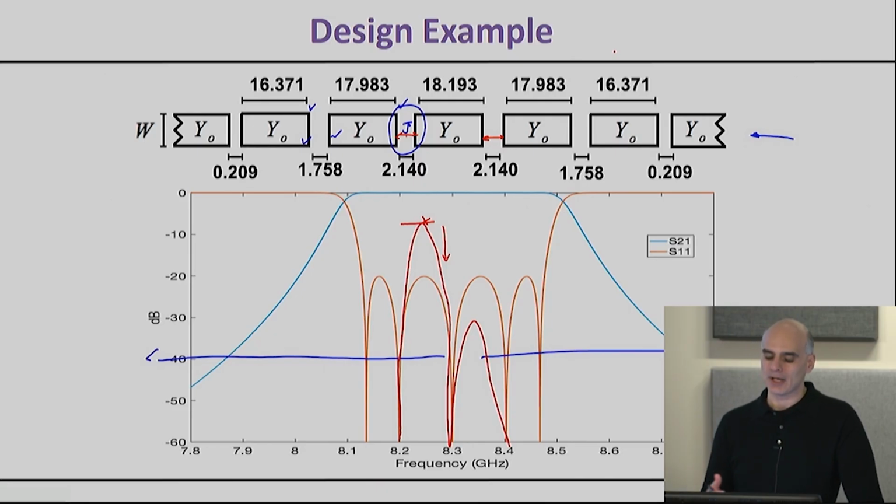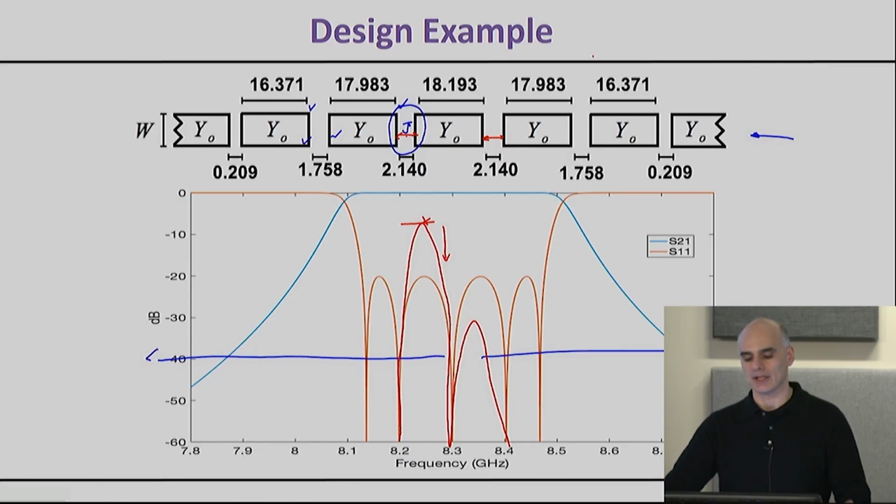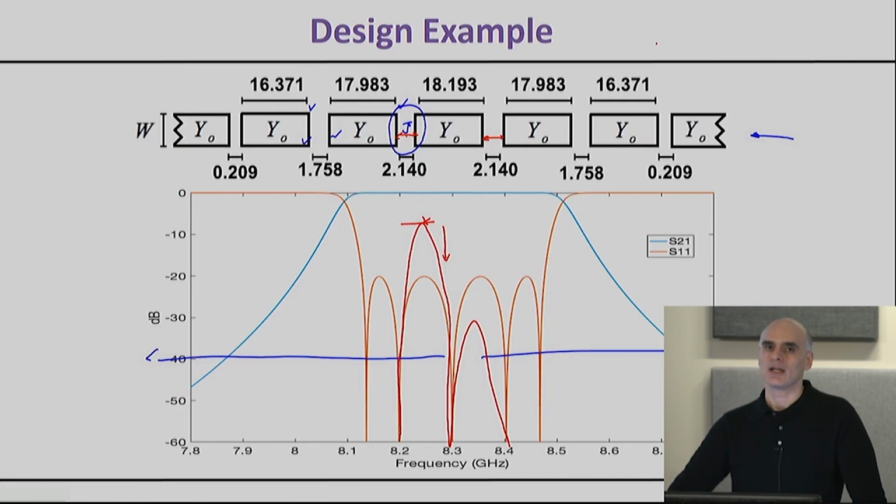Now, of course, then finally you'll have to make the circuit. You'll have to fabricate things. As I mentioned, there will be likely fabrication errors. So as the very last step, there might be some trimming that you need to do right on the layout. So it depends really how accurately you want to hit the response of your filter. But if you want to really hit the specs without any unknowns, it may take a couple of iterations to make your filter and basically trim it. Now imagine that this job is a little bit harder if you need to produce a few hundred or worse, a few million of those. And so in those cases, you need to understand your tolerances pretty well. And then that means you need to define tolerances in the specs that you can live with.